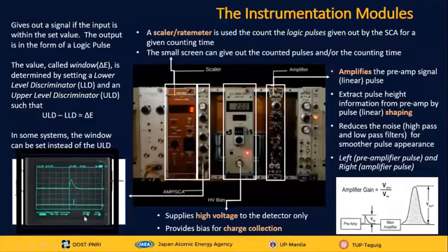This image on our left is a linear pulse and a logic pulse as shown in an oscilloscope. A linear pulse carries information through its amplitude and shape, whereas a logic pulse has a standard size and shape that only tells us the presence or absence of a pulse with a set pulse height.